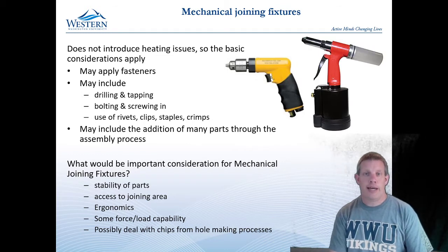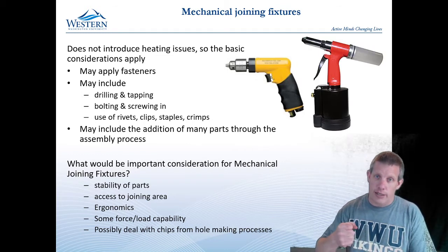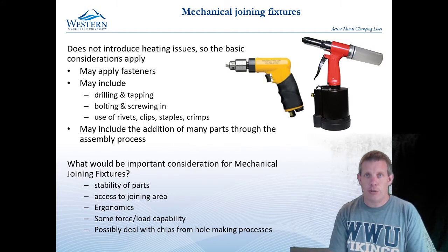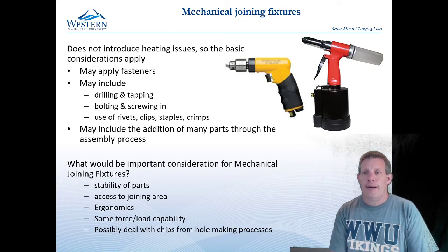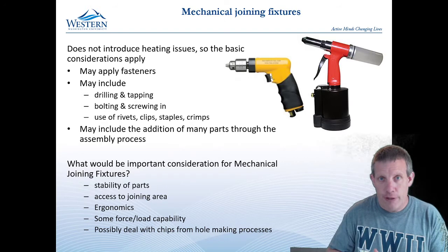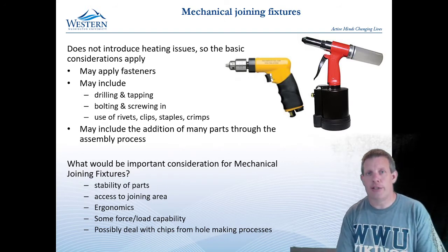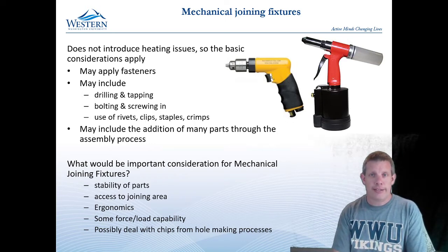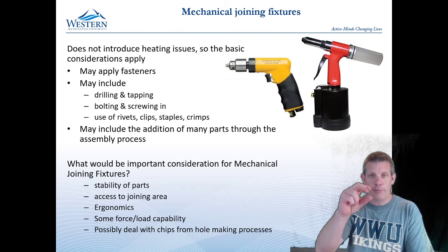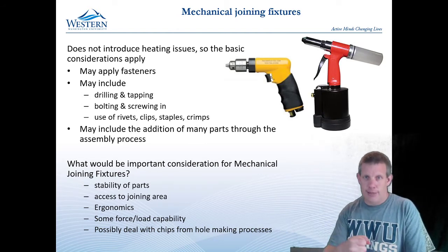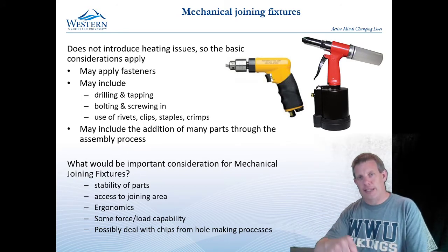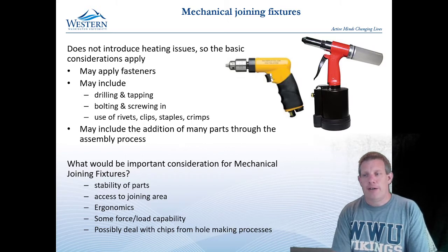We will also need to have some force and load capability so that we can put a fair amount of load on something. If you have drilled or tapped steel, it takes being able to apply a fairly good load so that you can go slowly and get that drill to go in there. You might also want something that would guide the tool, and so that would be a great thing for your fixture to have, would be little bushings on it, so that as somebody is putting these holes in, they don't have to center drill. They can just use a bushing and guide the drill at each point all the way down. And then you probably need a way to deal with the chips.